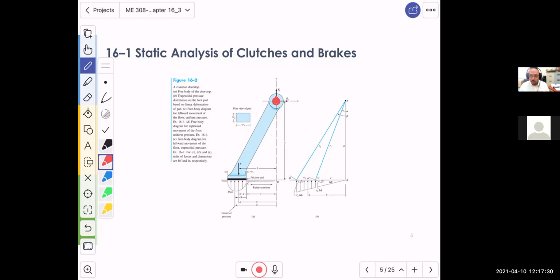Okay, so that frictional material will be pushed by the door, and the mechanism is inclined, so you will end up with a resultant force going downward, pushing against the surface. The surface will react by a pressure. Now here we're assuming that this door stop is a three-dimensional geometry. It's a rectangle, so the depth is going inside.